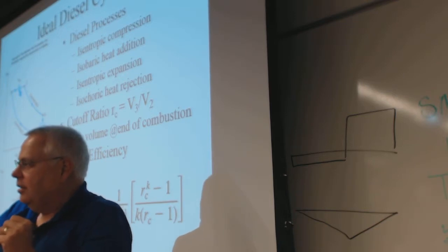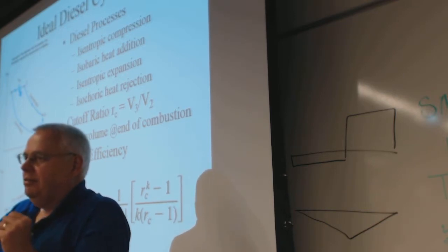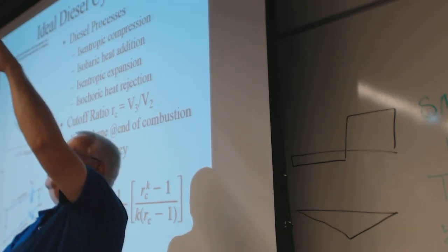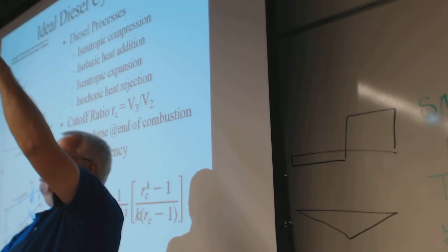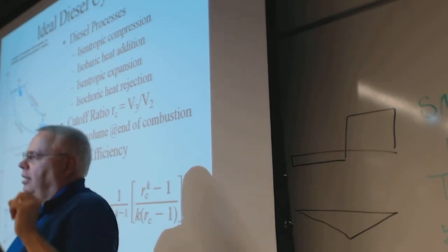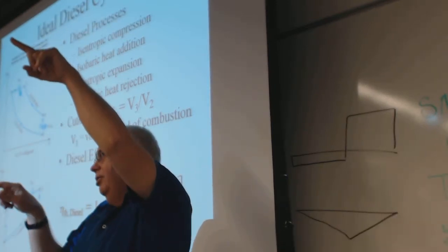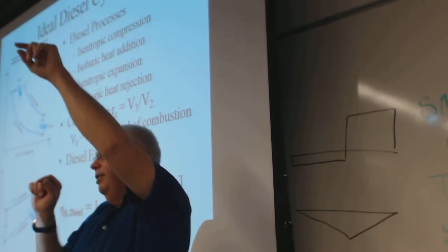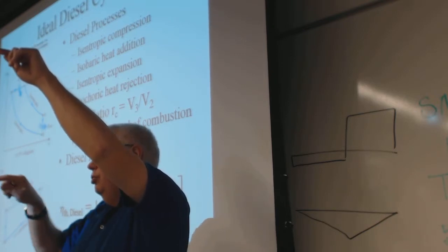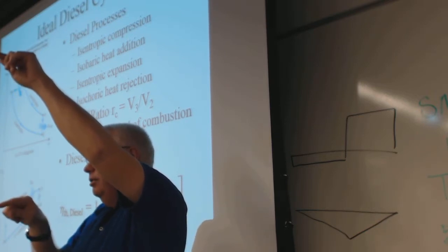But if it has an isentropic efficiency of 90%, it says it only used 90% of that total value. So it would follow that pressure curve out somewhere to the point where the enthalpy would be, well, it only used 900, so 1100 minus 900 would be like 200 kilojoules per kilogram instead of the 100.